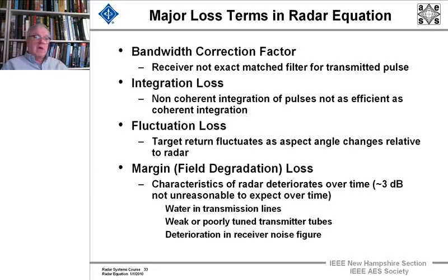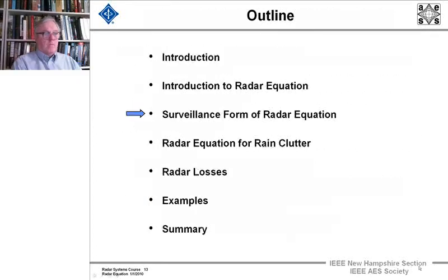So if you're a radar systems engineer looking at the whole picture, you have to keep track of all the different losses everywhere in your system, and make sure that every component that comes in is tested, that it met the loss requirements that were put in its procurement or when it was built. A disaster can happen cumulatively, even though one little subsystem might not seem to hurt that much.